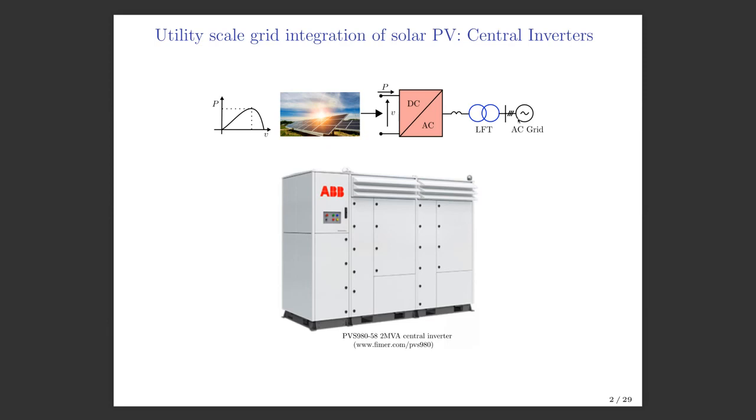Actually, there is a strong parasitic coupling between the solar cell terminals and the ground. This results in the flow of unwanted circulating or leakage currents, resulting in conducted electromagnetic interference or EMC, spurious tripping of the inverter, and power loss. Now, a transformer can break the path of this current flow.